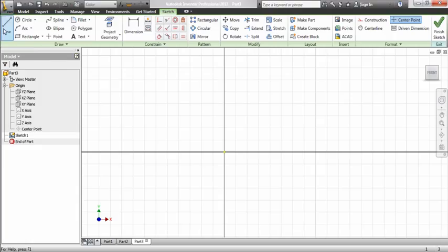So I'm going to go up to my line tool, and I'm first just going to make that top line of the T. And the top line is 2.25. Okay, when you add 0.75 plus 0.75 plus 0.75, it's 2.25.